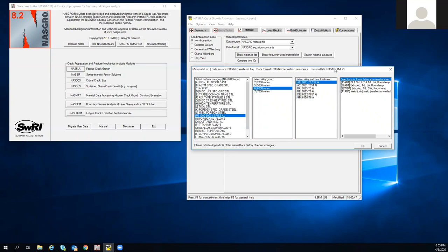to be involved in an anomaly investigation or disposition of a hardware nonconformance, something really important, every single time I would run these by a materials science expert to verify that the strength, the fracture toughness, and the crack growth parameters are all accurate and or bounding of test data of the hardware you're specifically trying to look at. So all of these properties will get you close.